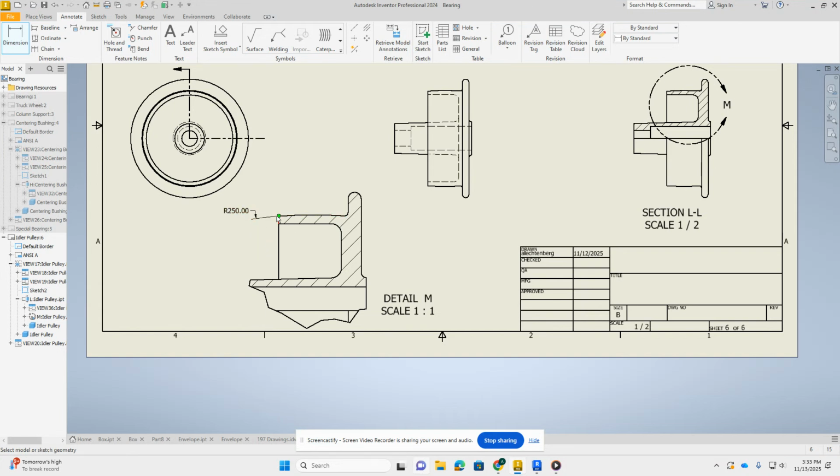For the 21, we click on this edge. We come out here, and you'll notice there's two green dots. There's 1, 2. We want the one to the right. So I click on the one to the right. If you go straight up, it should be 21. If it gives you this measurement, which is 19.92, hit escape, choose here, and go to the next button over.